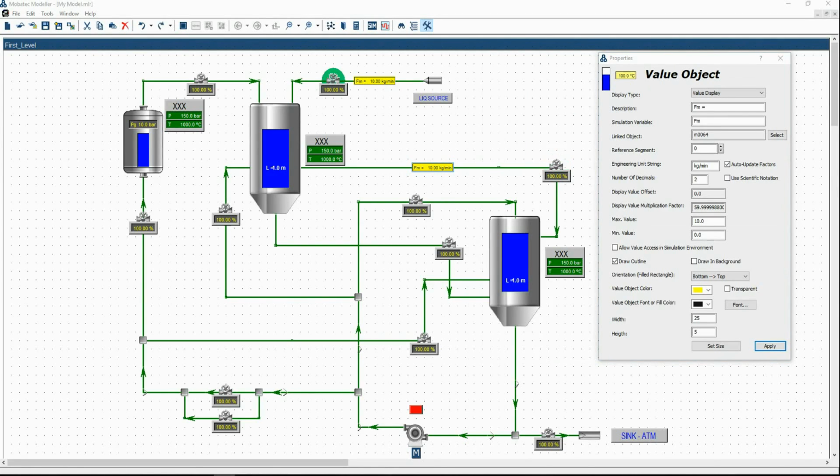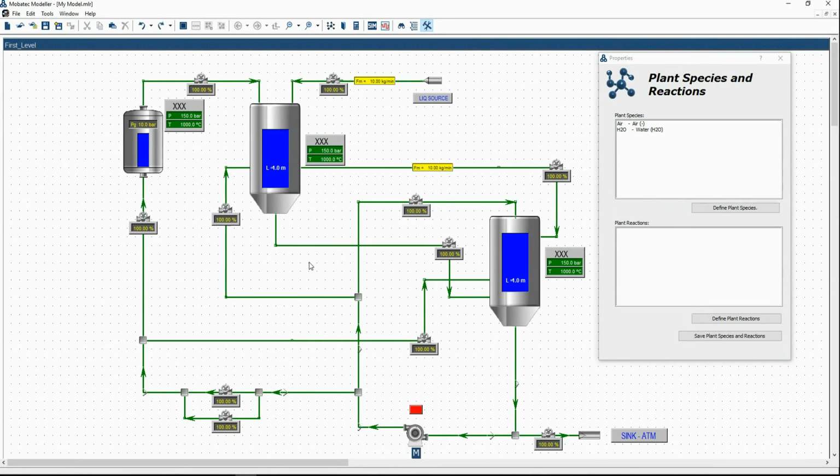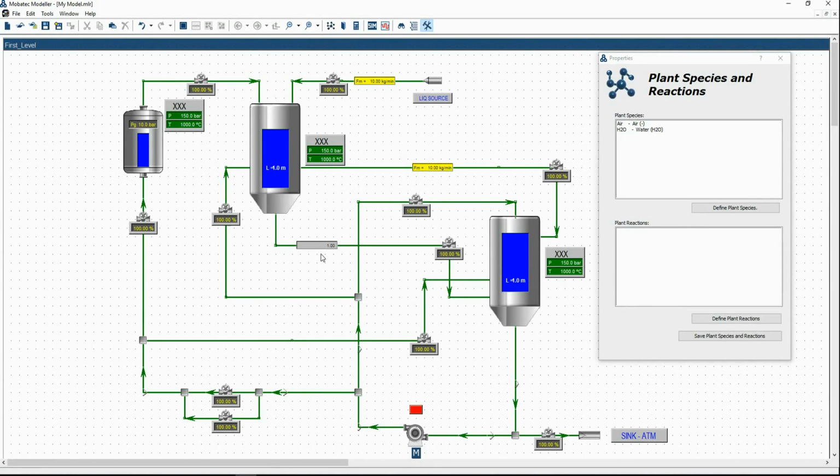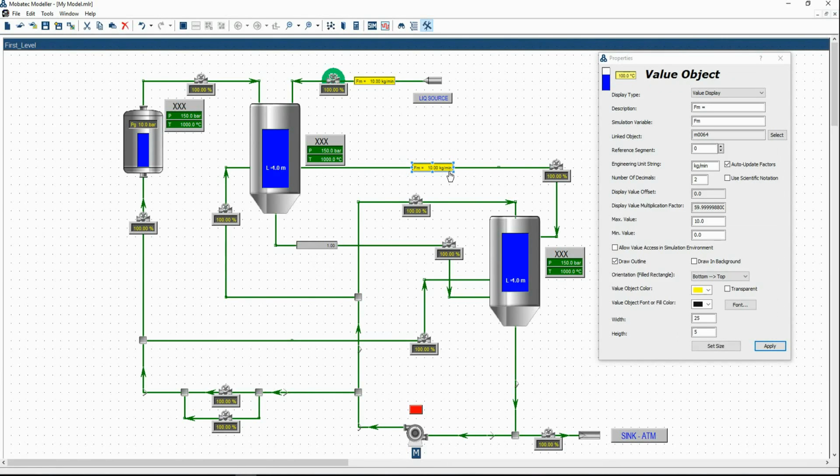What you could also do is to add a new display by pressing V on your keyboard, place it, let's say here, and then right mouse click to exit, and then copy the attributes of this display, which we already have defined, to the new display. Just select the defined display, press Shift on your keyboard, hold it and press V, like capital V, and then select the new display and just press V. We will see that the attributes are copied.